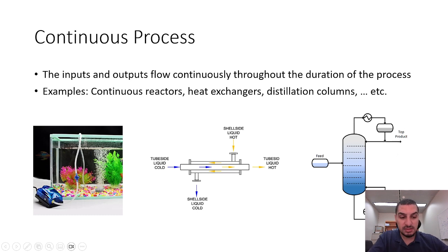And the opposite for the less volatile components that have high boiling point, so we collect them from the bottom. So this distillation column operates continuously. In general, we must have a continuous flow of feed into the column, and a continuous flow of the top product and continuous flow of the bottom product.